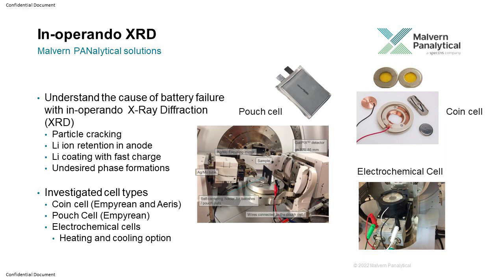Another thing that can happen is that lithium ions go into the anode, but then they cannot come out. Only some of them come out, maybe 60% come out, but 40% get stuck in the anode because your anode had a lot of defects and it trapped those lithium ions. So you can investigate that lithium retention. If you are doing very fast charging, then lithium can also do plating. Instead of going into the anode, lithium gets plated on the surface of it. And then you have a layer of lithium which is not contributing to any energy density, and it is lost out of the system.